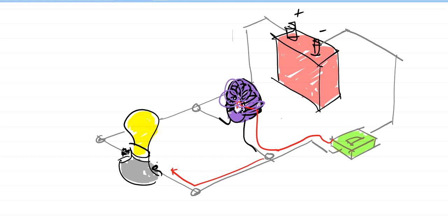Now when I try to turn this off, so when I turn this off, then there's no more power source. Then this inductor right here, because it doesn't want any change in the current, even though this is off, at some interval of time there's still going to be current flowing through right here. And somehow this light bulb still produces some light, right, at some interval of time.